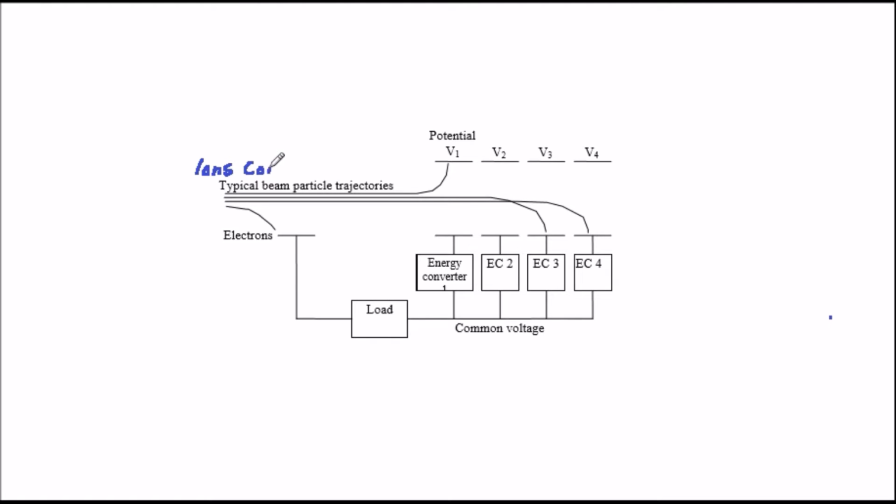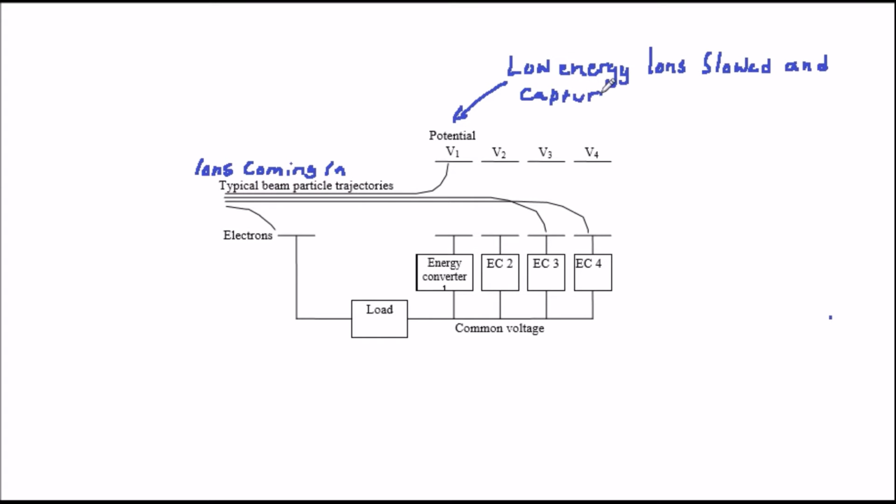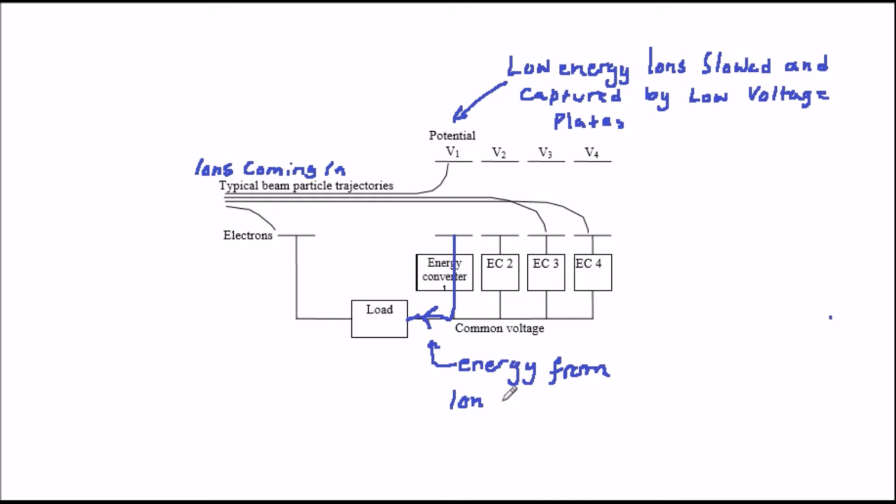Fortunately, there are ways of getting energy back from scattered charged particles, and these can be divided up into two techniques, a DC method and an AC one. Let's start by looking at the DC method. This technique is used in some high-powered valves, or electron tubes as they're known in the USA, like klystrons and gyrotrons. It consists of a number of catching electrodes at different potentials.